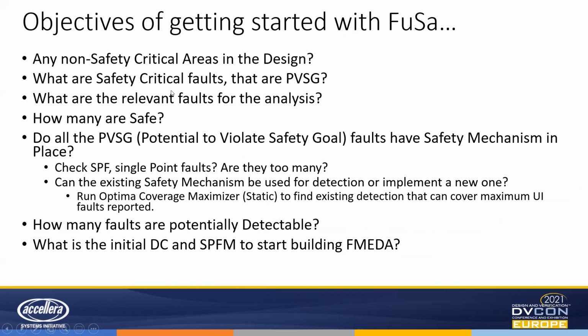And also, what are the safety critical faults? If I have some safety critical blocks in my design, are they violating the safety goal, which we call PVSG, potentially violating the safety goal? And what are the relevant faults for the analysis? How many of them are safe? And do all the PVSG faults have the safety mechanism in place? That's what ends up in calculating our SPF, single point faults, which don't have a safety mechanism. Are there too many? Or can you sign them off as not requiring any safety mechanism?